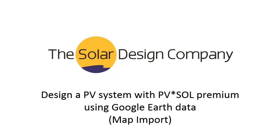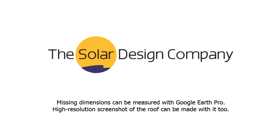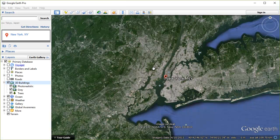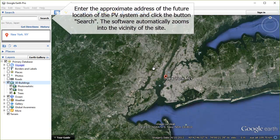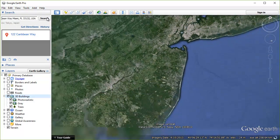Welcome to a video tutorial on PVSOL Premium 2016. And we're going to look here about using the map import feature and extrusion of 3D objects. And we use this in association with Google Earth Pro, which means you would start that up separately on your computer. Notice there are two versions of Google Earth. It's important to get the Pro version to get the right ruler measurements that you want to use.